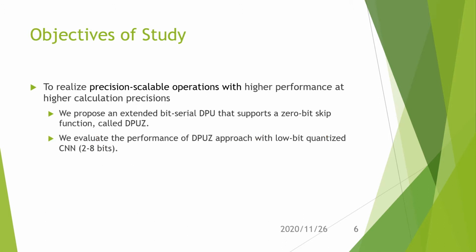Our objective is to realize precision scalable operations with higher performance at higher calculation precisions. We propose an extended bit share DPU that supports a 0-bit skip function called DPUZ. We evaluated the performance of the DPUZ approach with low-bit quantized CNNs from 2 bits to 8 bits.